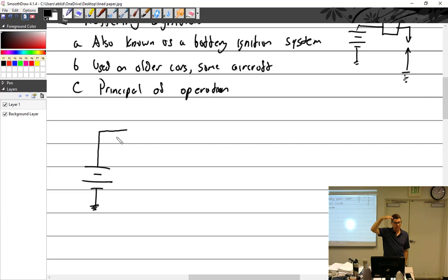I mean, it doesn't keep rising, it's just woo! It's just a big jump in exhaust gas temperature. If your exhaust gas temperature goes up, that's somewhat of an indication that you have an impartial burn and it's burning later. So less efficient. You're losing heat out of the exhaust pipe, and it's a heat engine, so if you're losing that.